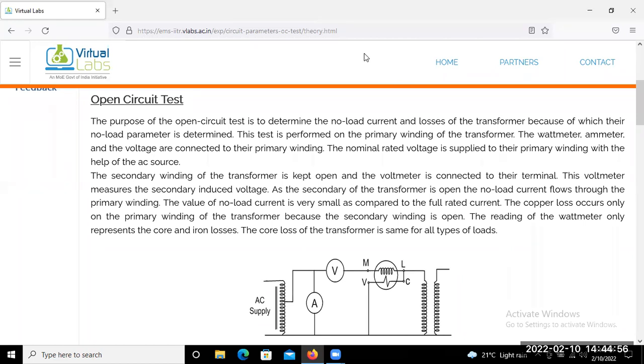Yes, sir. Okay, so you have to keep these 2 points. We are not able to measure 11 kilovolt or something like that with a standard measuring instrument. A standard voltmeter and ammeter has a rating of maybe 5 ampere or 10 ampere for the ammeter, and 230 volt, 400 volt, up to 440 volt, or single phase 230 volt.